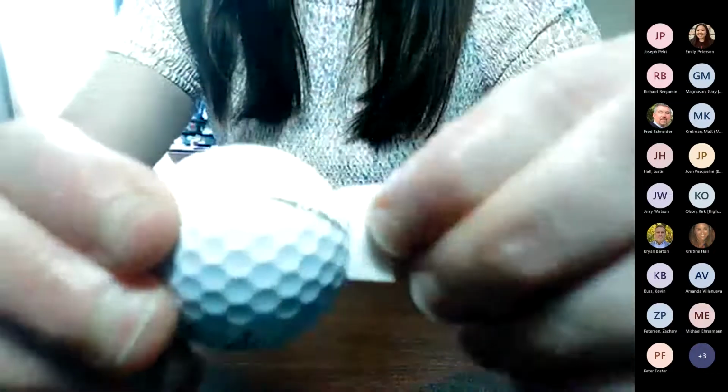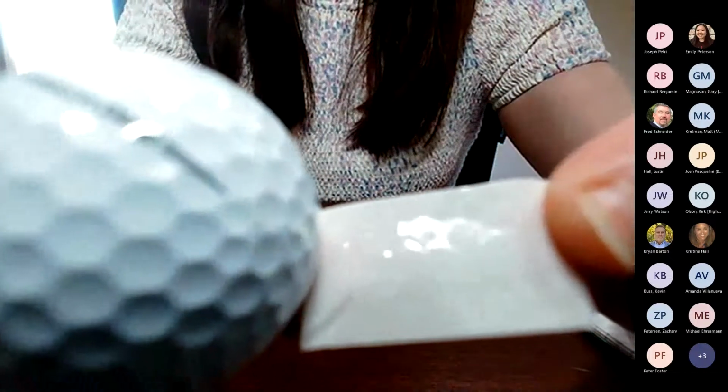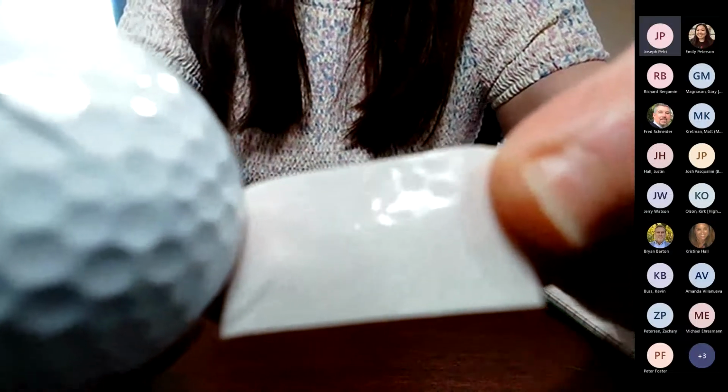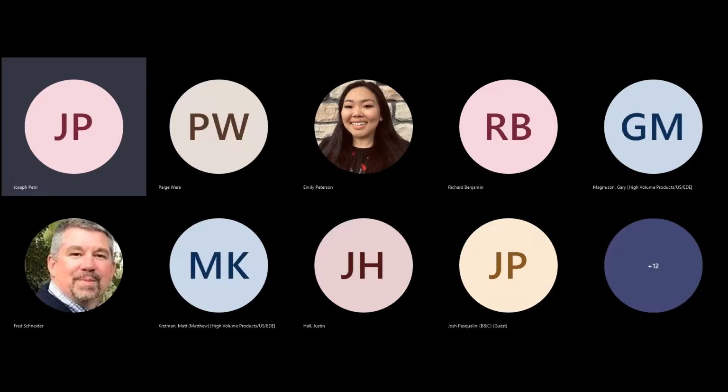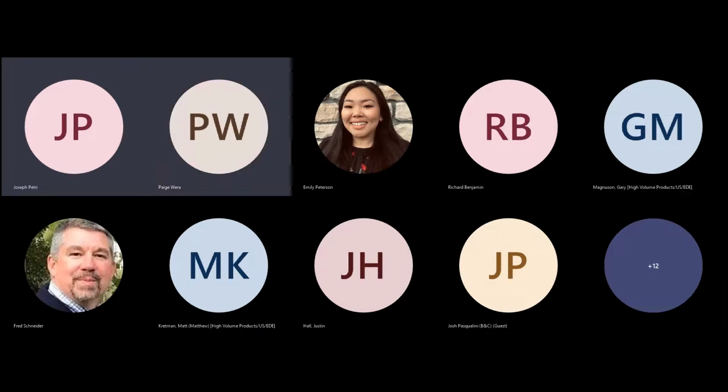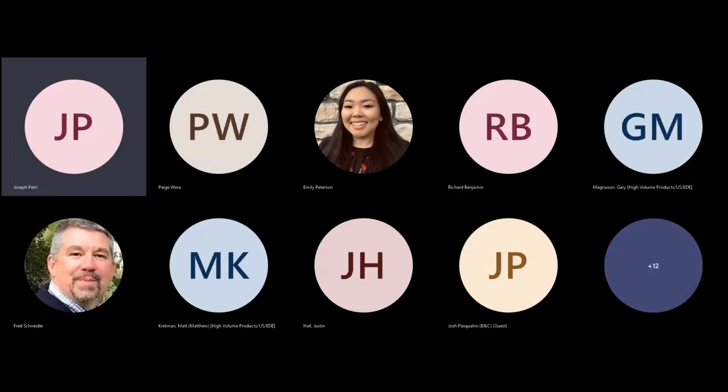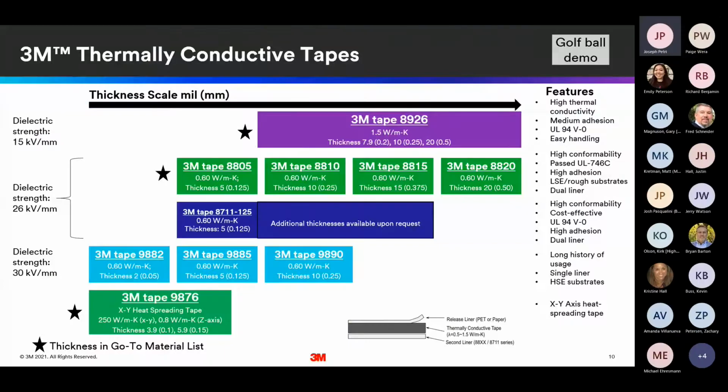And then when I do this kind of test here, you can see the dimples a little bit better, showing that wet out and the full heat transfer. Yeah, so that's good. Hey, these thermal tapes have been tested to the UL 746 C, which is an environmental enclosure testing, where it sees thermal and humidity cycling. And these actually perform quite well in some of these high humid and more difficult environments that an LED light or some sort of system could find itself having to function in.